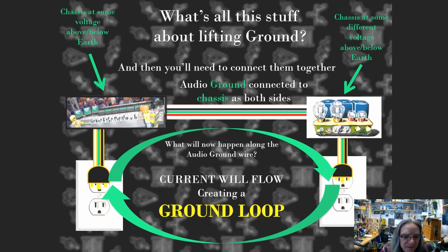And how we fix that, we'll be talking about. One easy way to fix it, all we really need to do, right, is make it so that there's not a connection to this loop. So at any point we can disconnect this loop. A physically easy way to do that would be using one of those grounding adapters without using the screw to ground it properly on one of these two outlets.